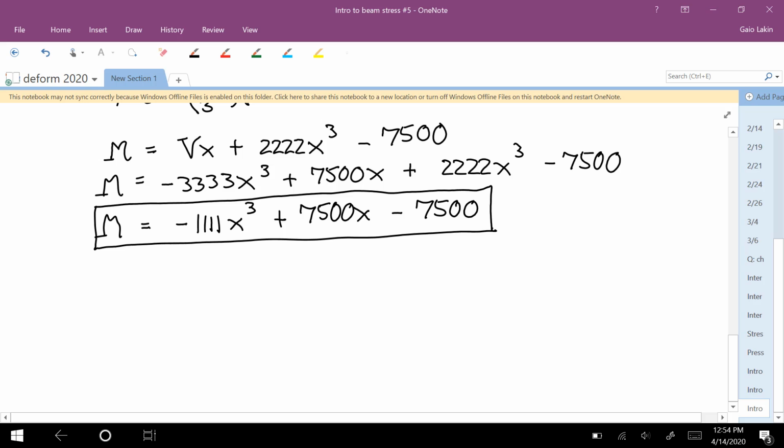Okay, so now what's the greatest absolute value of normal stress in the x direction for this beam? Well, so now we're going on to part B. The total stress tensor, well, let's say you can also do this piece by piece. So the total x normal stress is the x normal stress from tension. That one is 0 because the tension is 0, plus the x normal stress for the bending moment. So that's the only one we have to worry about.